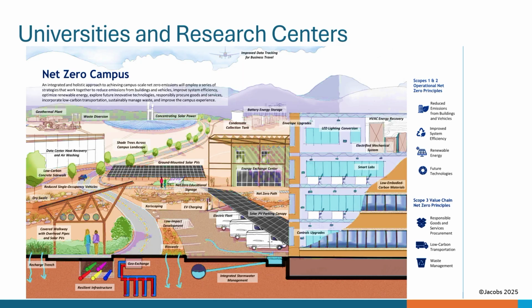But the neat thing about this one was we looked at everything for them, right? We looked at everything from business as usual, which was maintaining existing gas-fired boilers for a central steam plant serving the whole campus, to decentralized chill water plants that were all in separate systems that weren't interconnected, and then a whole bunch of options between that extreme and the extreme of cross-connecting the entire 60,000 person campus on one thermal energy network, with a few geothermal bore fields and some waste heat recovery from sanitary sewer.